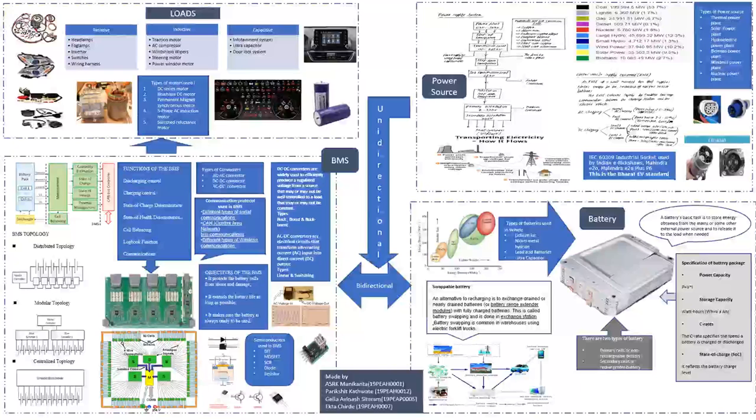And coming to the materials used for the transmission of electricity. Electricity lines use copper, aluminum, cadmium copper alloy, phosphorus bronze, steel core aluminum, and steel core copper. Copper and steel core aluminum will be used more because aluminum is very light in weight, and copper has high tensile strength. Copper will have high tensile strength.